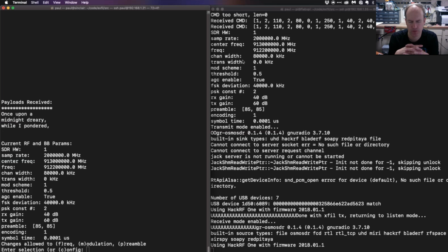Well, yeah, with an SDR using a GNU Radio interface, there are ways to pare this down a little bit, but as a back-of-the-envelope calculation, you're generating a complex sample each time with your SDR. If you're sampling at, say, 1 megahertz, that means you're generating 1 million complex samples every second, and each complex sample is two 4-byte floating point numbers.